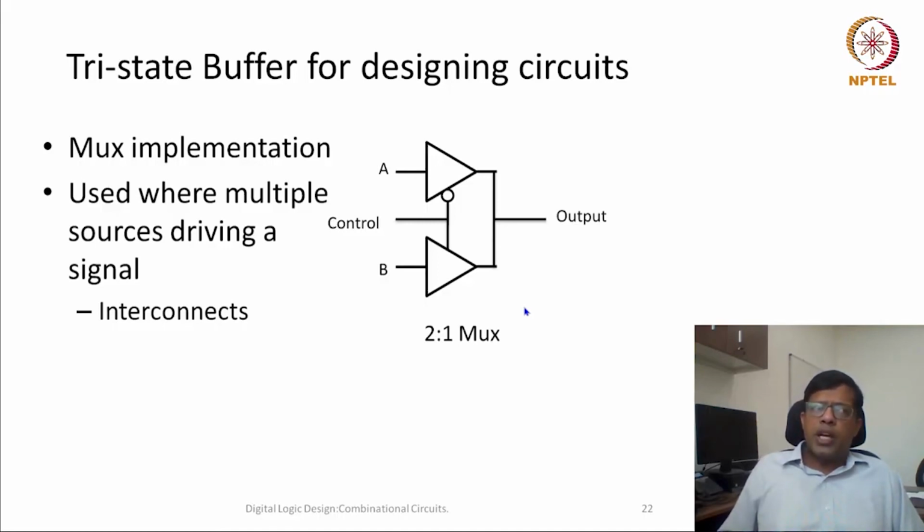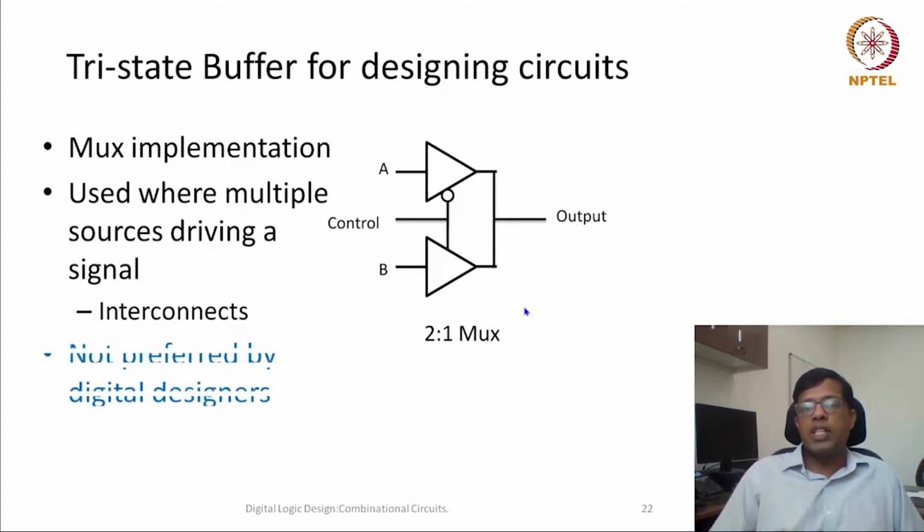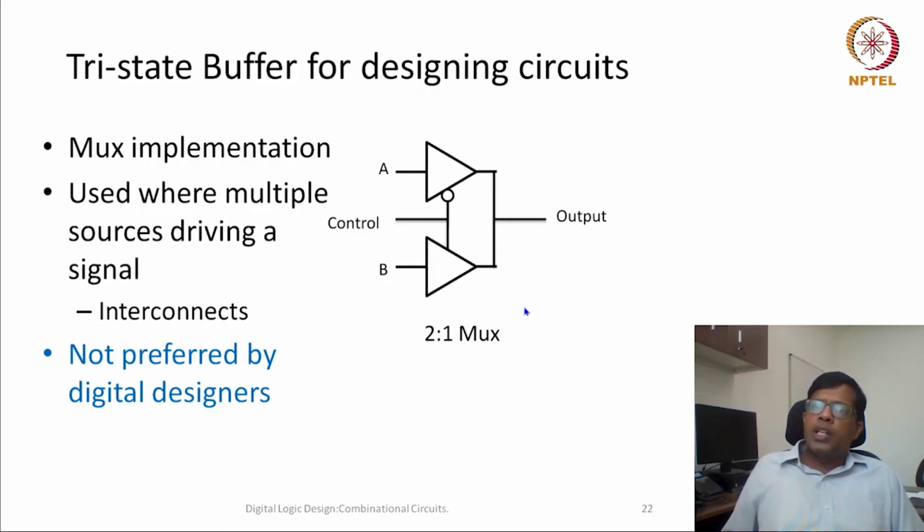Earlier, like some 20 years back, when we were in the nascent stage, when we started designing these VLSI chips or digital circuits, at that time these tri-state buffers were very, very popular. But these days, when we are automating most of the design, when we are using Verilog to design the final hardware, and when most of the designing is done by the EDA software or synthesis software, these tri-state buffers are usually not preferred. We are teaching this to understand a couple of these concepts.